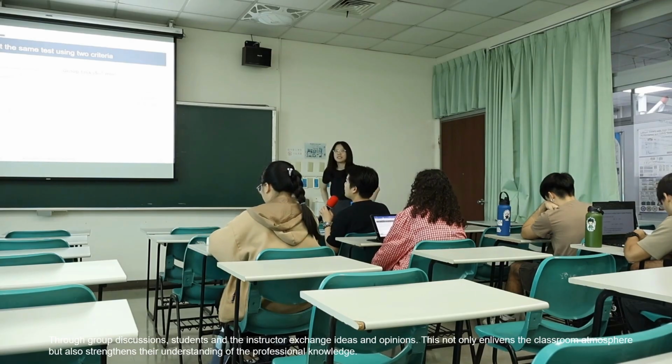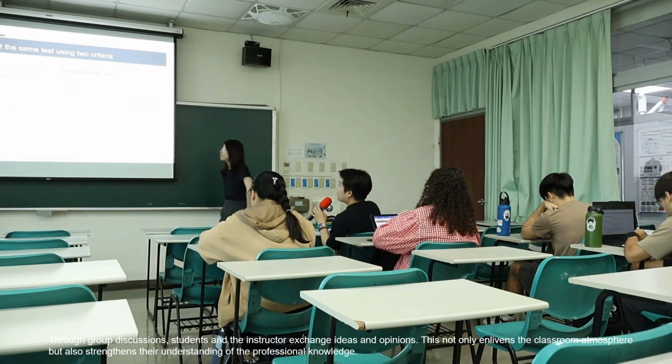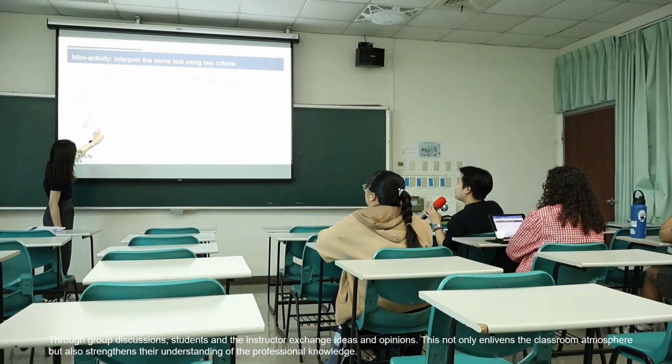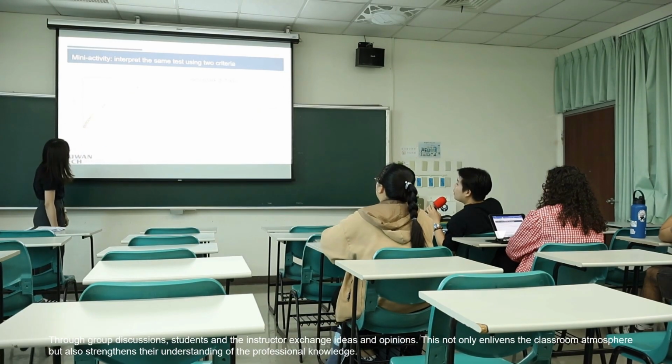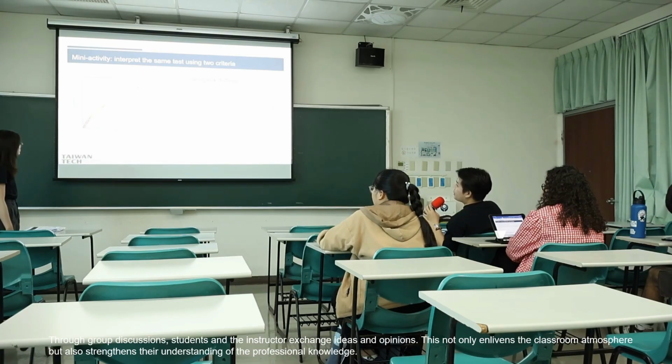So we can get the capacity is around 126 allowable. In this case, we need to take a capacity less than the allowable capacity. So we assume 100. Based on the y-axis, we can get the settlement is around 4.7 millimeters. The allowable settlement requirement is 6 millimeters, and from the x-axis we can get the load is around 140 or 150. So we compare the allowable load with the 140 or 150. I think the pile is governed by the capacity.